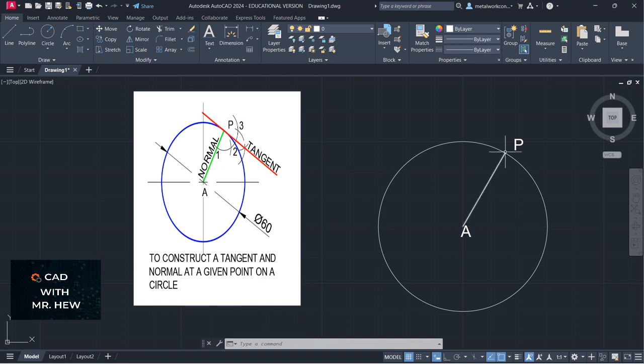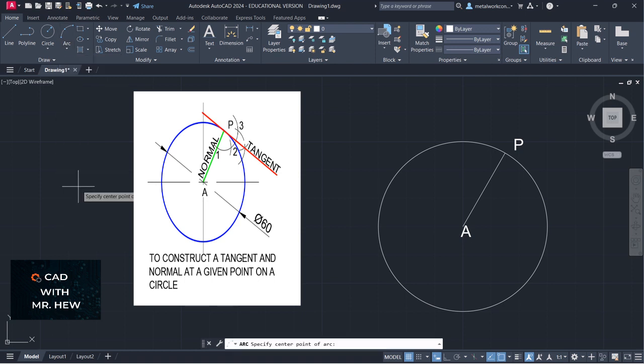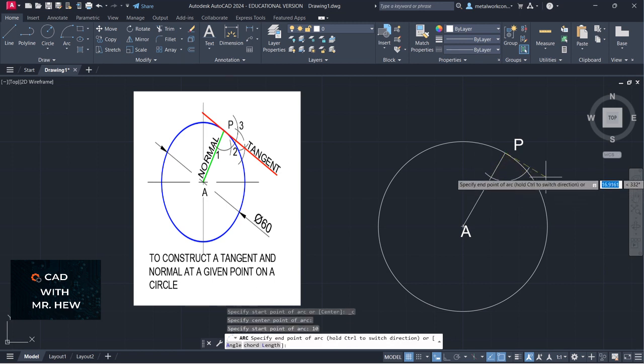All right. I'm going to show you how to construct the perpendicular at the end of the line without actually extending it. Okay. All right, so this is what you would do. You would go to arc, center, start, end. So the center would be here. The radius, we can make the radius 10. And look now, come across and we go across like that.